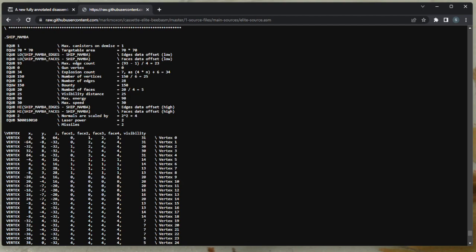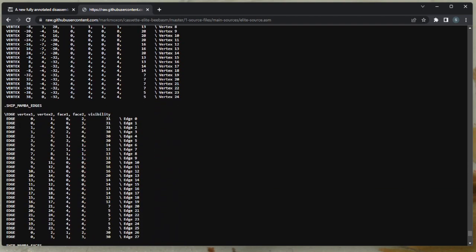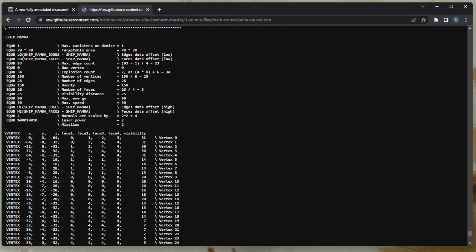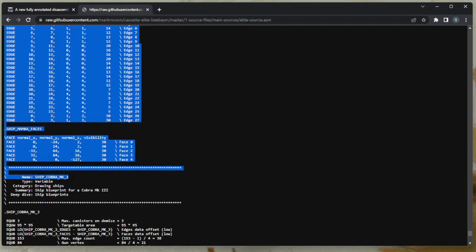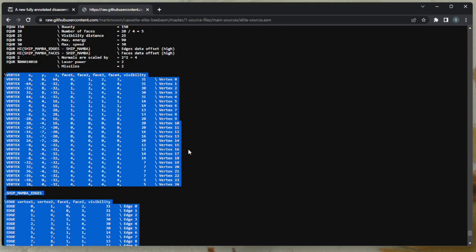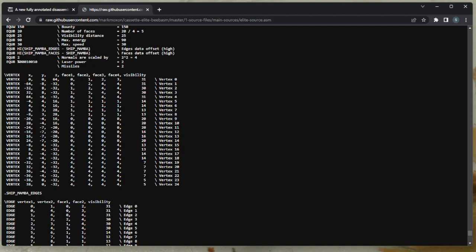I've not used the face information. Here it's got the edges, and so I've used those, I've called these connections, and then I've used the faces. So every edge obviously is on two faces, and then it's got the normals to the faces down here. So I've used those three parts. So any file that you've got that uses those three parts, you can just put straight into the Python script, and that will produce the format that you need for the assembler. Just basically rearranging it.